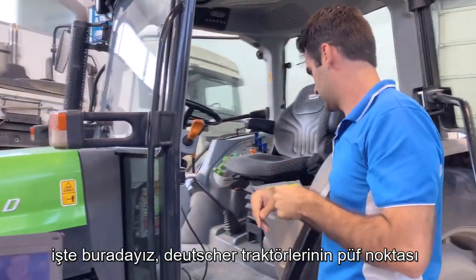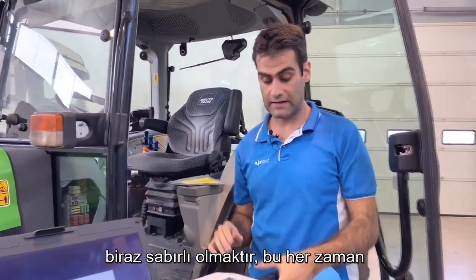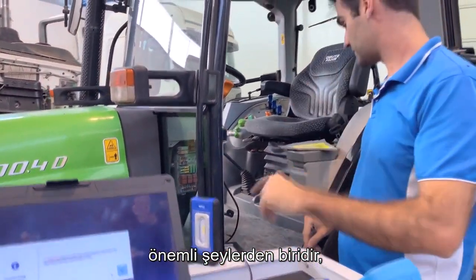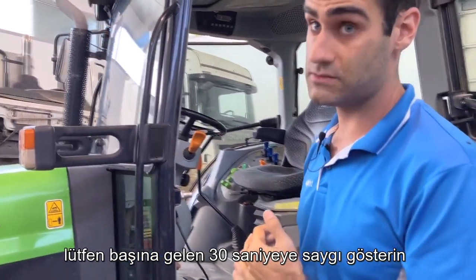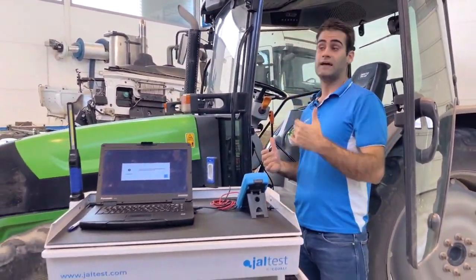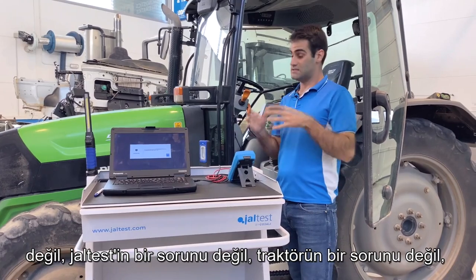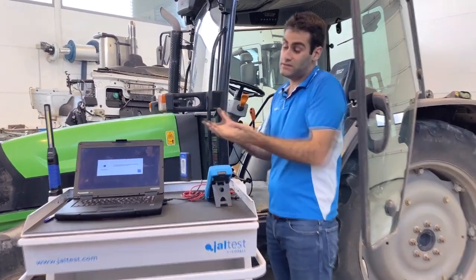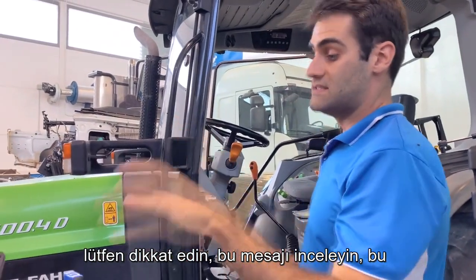There we are. The trick with Deutz-Fahr tractors is to have a little bit of patience. It's one of the most important things. Always please respect the 30 seconds. It happened to me. I waited only 10 seconds, I even didn't switch off, and as I told you, it did nothing. And it's not a problem of the diagnostic device. It's not a problem of Jaltest. It's not a problem of the tractor. It's a problem of we didn't read the instructions correctly and we didn't do it correctly. So please pay attention, check out this message.